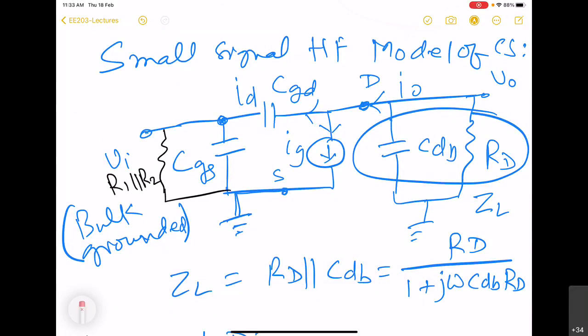And of course this RS will be there, and this intervening capacitor Ci will act like a short circuit, so we need not include it here. So now Vi is going to be this voltage. This is going to be the modified circuit, for which you will have to once again find out the transfer function, that means Vo by Vi.